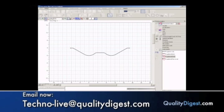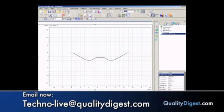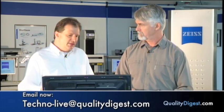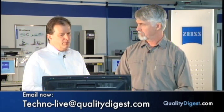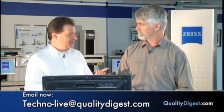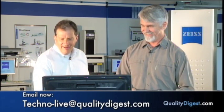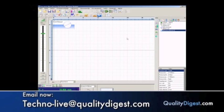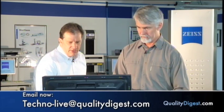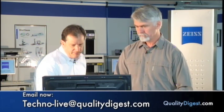So that was the end of the trace. There we go. That trace is complete, and we're automatically sent into the analysis screen. But before we do any analysis, I'm going to jump back to the measurement screen just shortly, because I want to make a move. In most cases, when the measurement finishes, we might want to get the instrument away from the part so that it can be replaced, to put a new part in, and again to protect that expensive stylus. So it also probably speeds things up. This is just one less move the operator has to do. Exactly. So we're going to just put a quick move in.